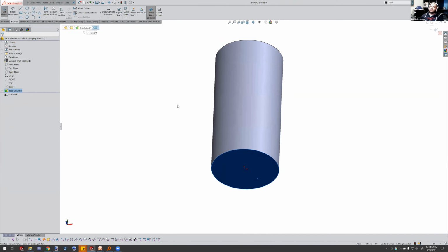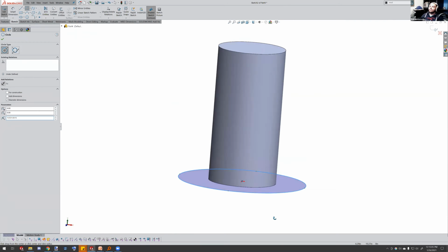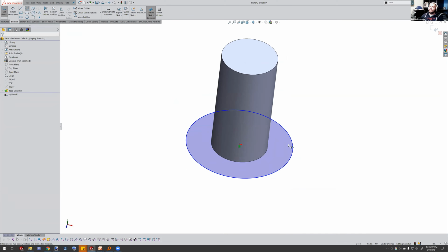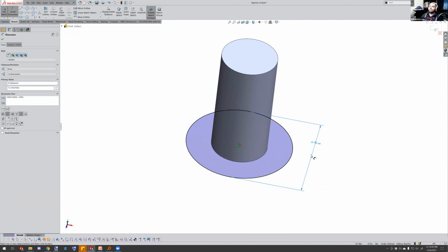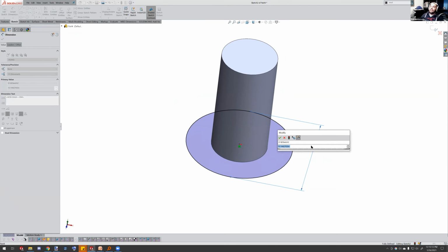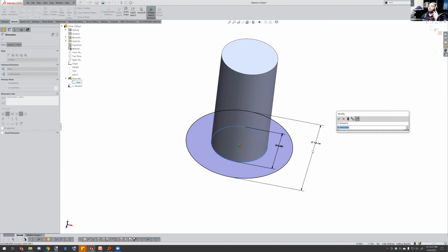So it doesn't look very hat-like. Maybe I want to make a brim or something like that. So I can draw another circle like that, and give it another dimension. I always want to make sure that it has a brim, that if I resize it, it doesn't lose its brim for any reason. So I can use its parameter-driven knowledge to drive it.